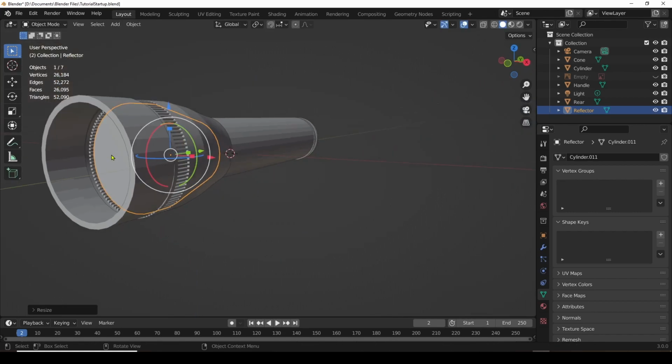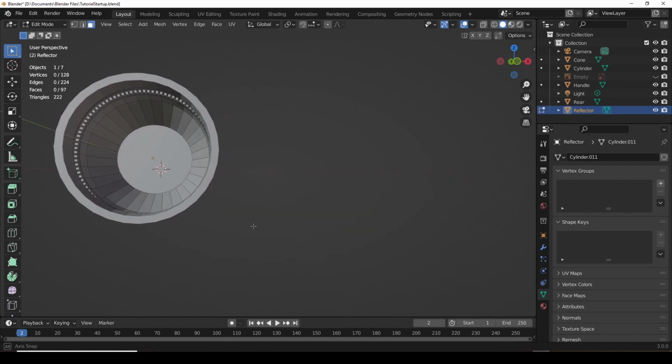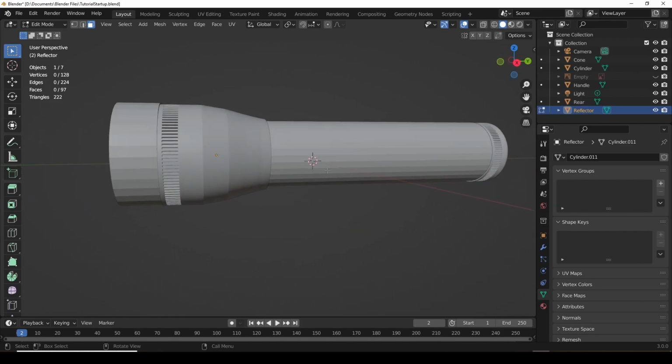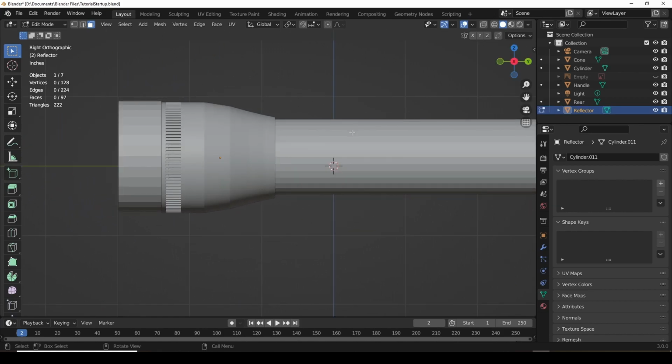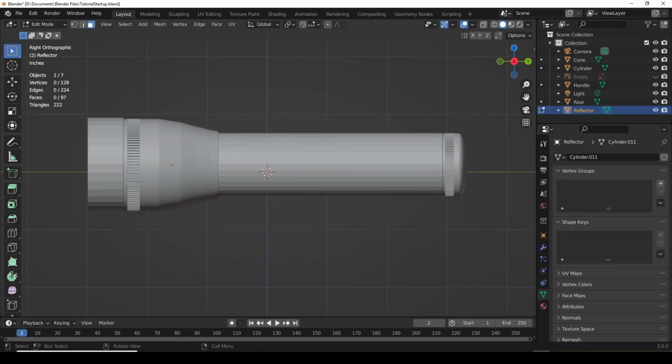Now again, we're going to have to get rid of this face here. So we're going to go to Object Mode, Edit Mode, Face, click on this, hit Delete key, Faces, and now you have deleted the front face. So now we're pretty much done. We've got our object modeled. We got all 5 pieces modeled.